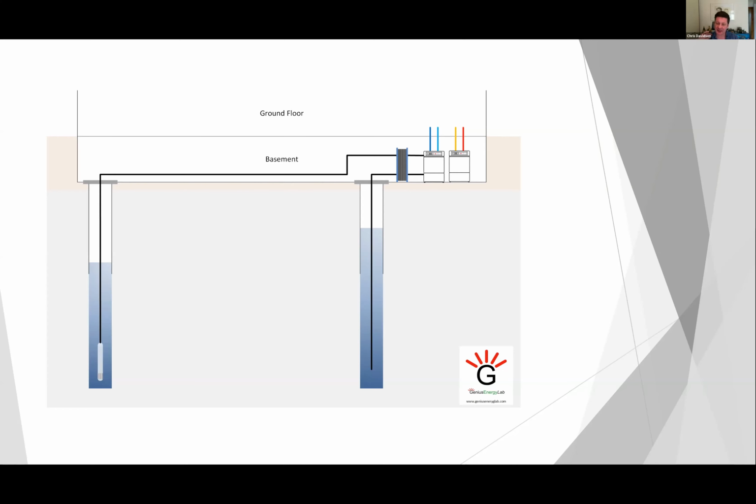However, certainly in larger systems, it is almost always the case where you break the two circuits, keep them apart, so as to protect the heat exchangers inside your heat pumps, which are much more difficult to replace or repair than these external plate frame heat exchangers, which could go in duty standby pair, so you don't even have to take the system offline to do some maintenance on those heat exchangers.